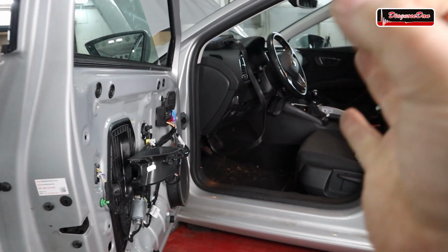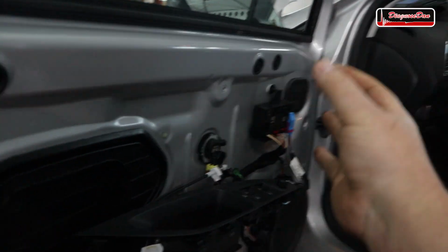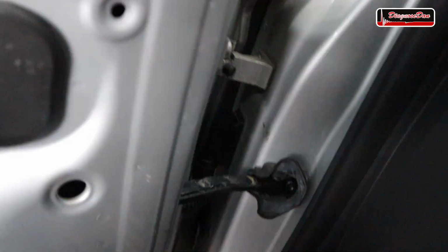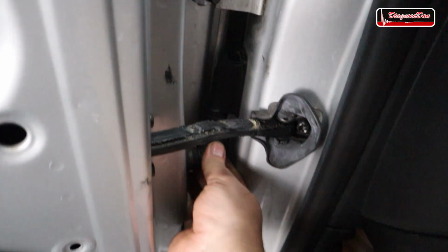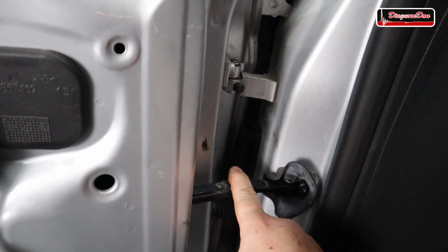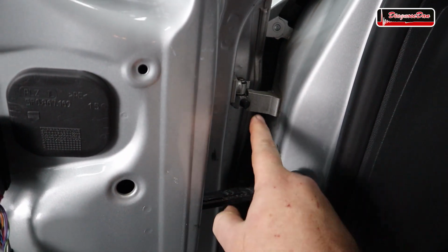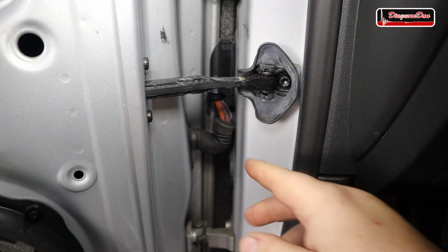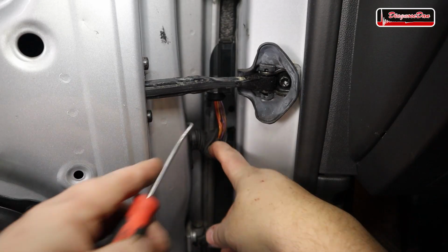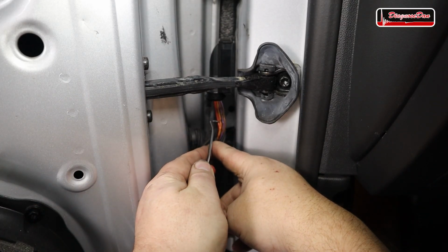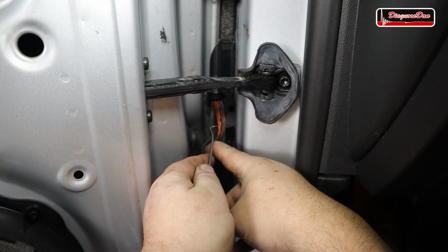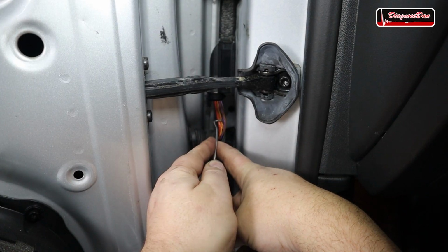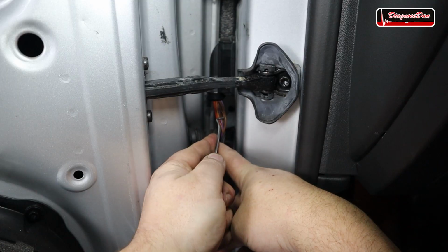Now, the first thing a technician will check when you have problems with any electronics in your door is the wiring harness of the door at the hinge right here. The other shop told me they've already checked it, but just to be sure, we're going to check it again in the front and in the back. This is the driver's door, and I pulled the grommet down, and now the wires are revealed. I'm going to pull those wires with a hook, one by one, quite firmly, and if one of those wires is broken, I will be able to pull it out.